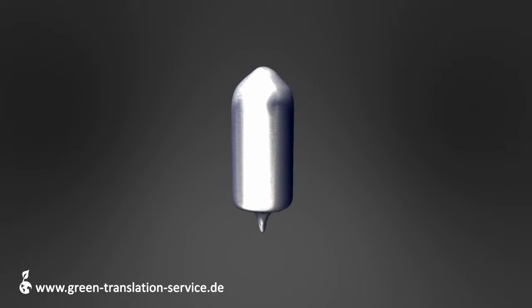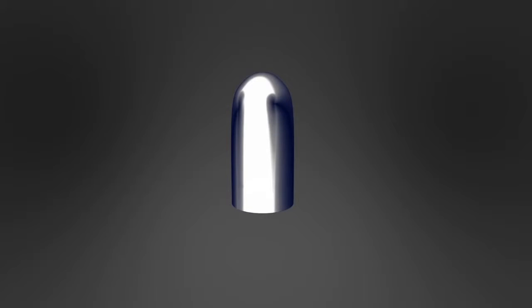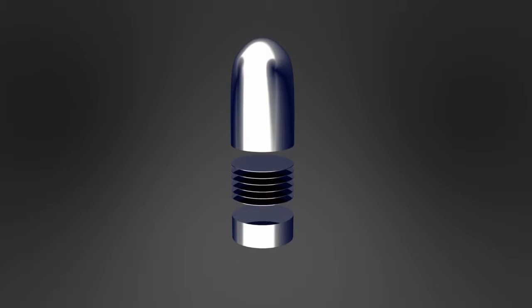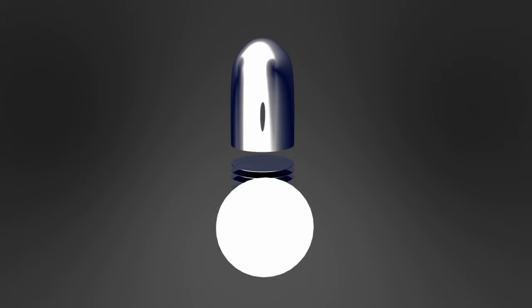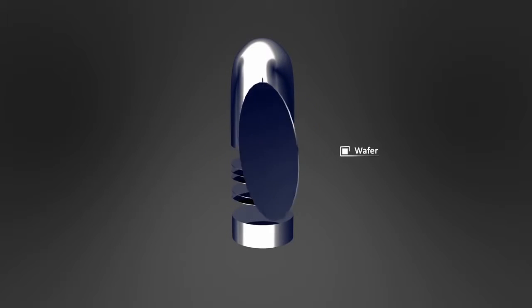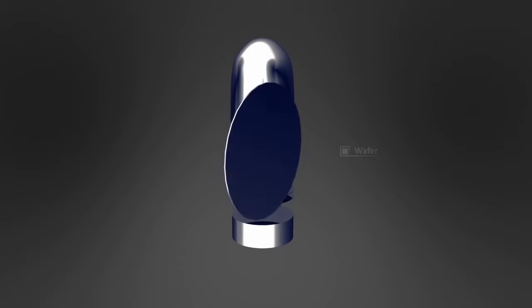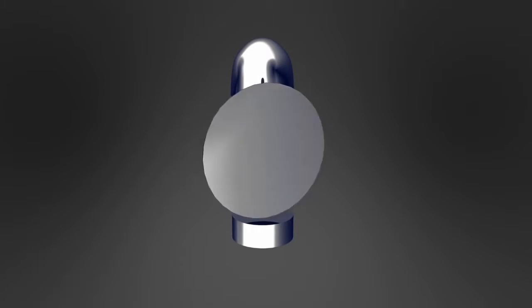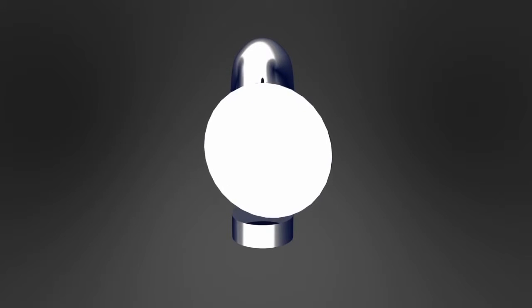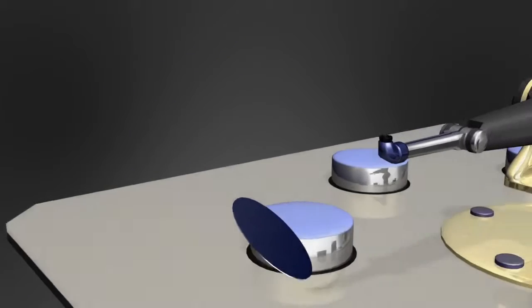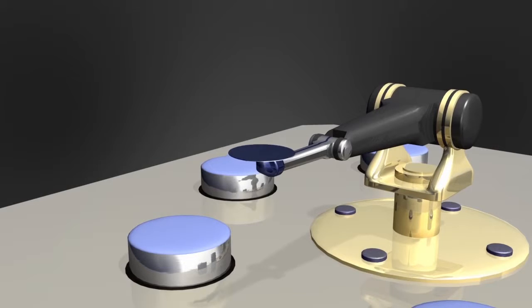The block is cut into wafers of the desired thickness, anywhere from 0.5 to 1.5 millimeters, depending on their intended use. The wafer is then polished and subject to rigorous inspection. If the wafer passes the subsequent inspection, the first step of production begins, which is called front end of line. Here, the integration of transistors takes place.